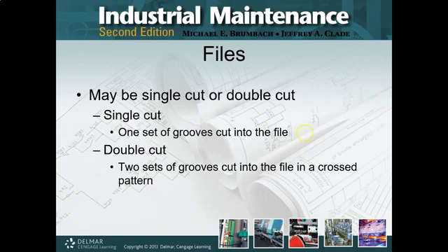Really nice. Single cut are nice because they're easy to clean out. Double cut are nice because you get a lot of cutting done, and it's usually a finer cut. But the catch is those tend to load up really quick and are really a pain to clean out.